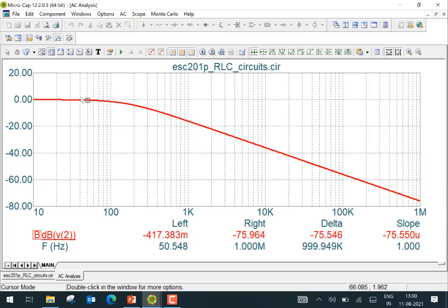Let's do that 3 dB. Because this is very close to 0, it would be approximately minus 3 dB here. So let's go to minus 3 dB, right here. The 3 dB frequency for this particular filter is 158.876 here. And you can verify it with the formula that we have given for the 3 dB frequency, how closely it matches with the expression that we have here.